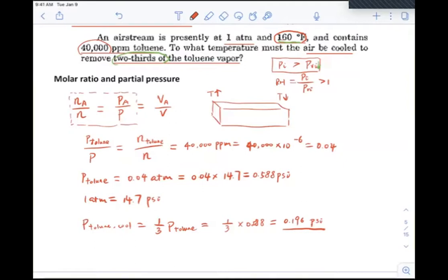So it's very similar to the gravitational settler as we introduced earlier. For the gravitational settler, we don't create a chamber to remove the particles. These particles automatically settle down by themselves in the duct, so everything happens by this natural process. We don't have to create the condition where we either lower the temperature or promote the gravitational settling. So I would say this condensation method is very similar to the gravitational settler. Both of them are passive methods, so it just happens by itself.